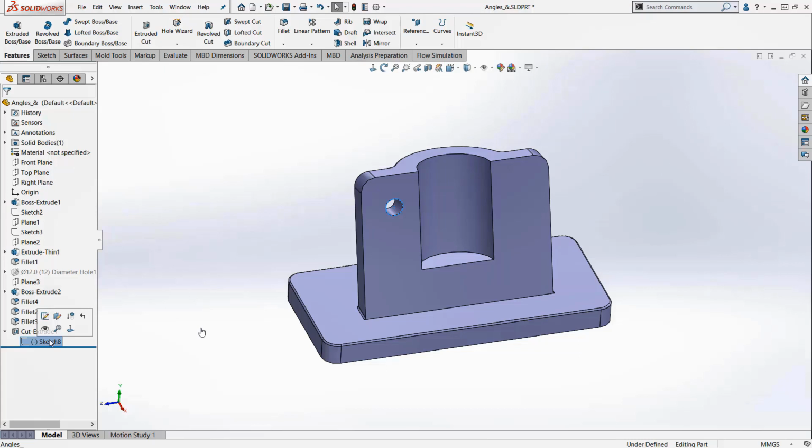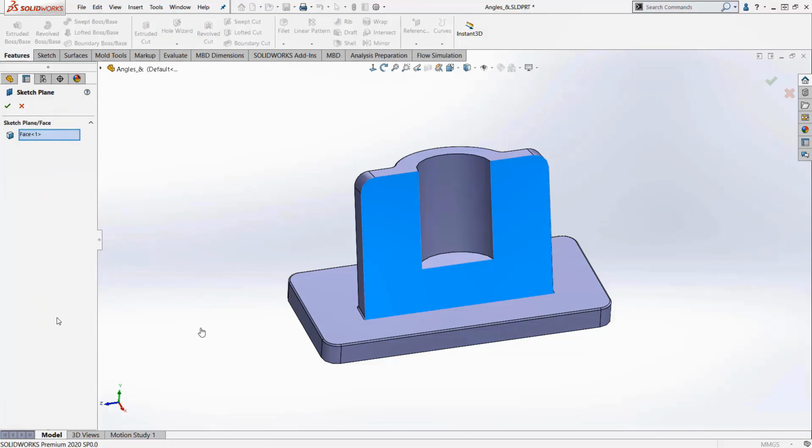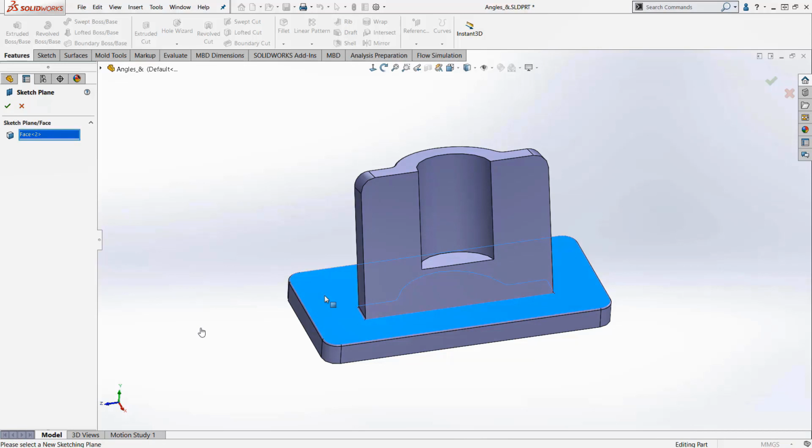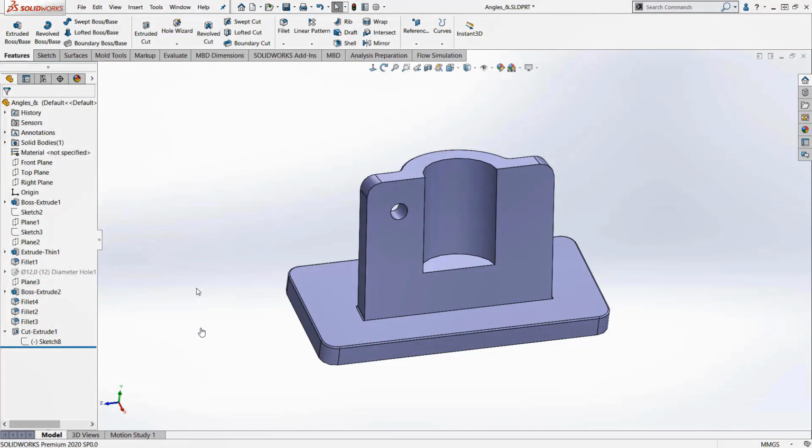Here I clicked on the sketch, edit sketch plane. If I wanted to reposition it, this is the way we teach you how to do it. This is the more straightforward way. I want to put it on that base face. Click right there, hit OK, and it'll relocate that sketch, but it's going to be off to the side, or I'll get a rebuild error like that. Okay. Now, if I want to do it dynamically, here's the tip.